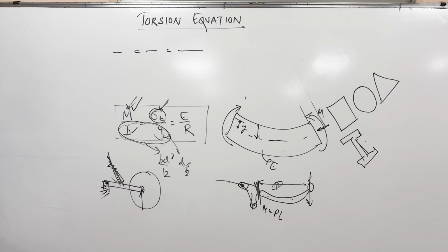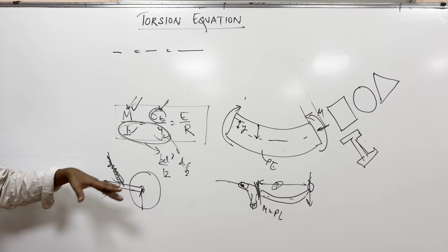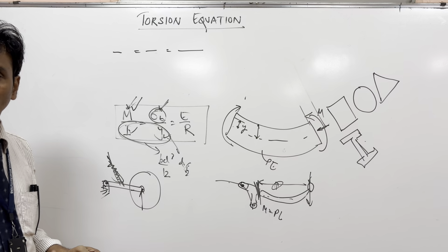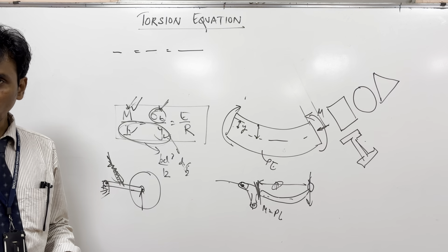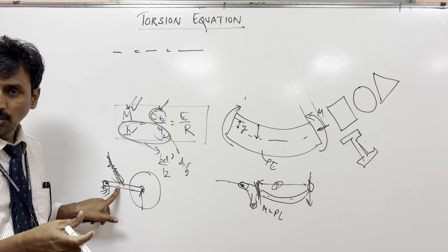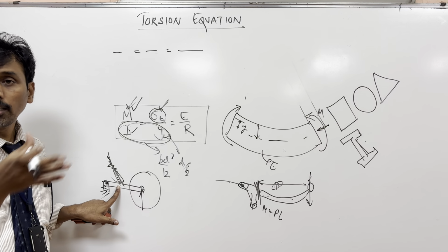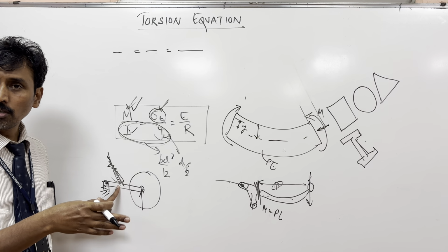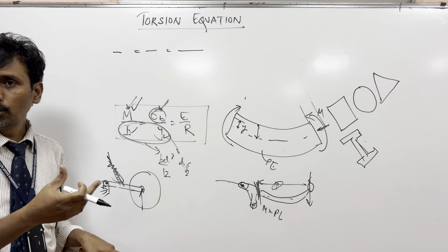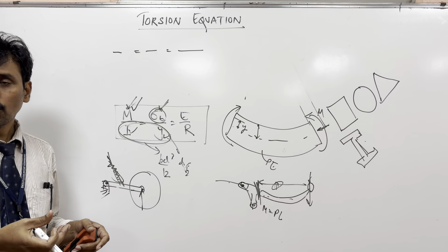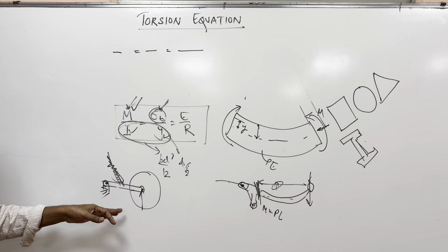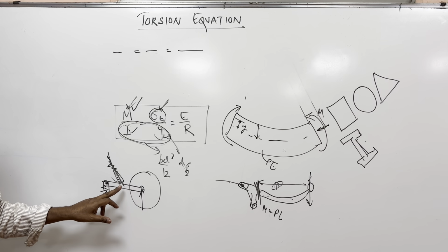When you want to design a swing arm, you should be able to initially start with some values of the sections. We would have observed different types of swing arms. Are they circular? They are rectangular in the newer bikes, but they were actually circular in older bikes, like Hero Honda and all. It was easy for anybody to make circular rods, so it was usually circular. Nowadays it is coming as rectangular sections. So you can definitely know that.